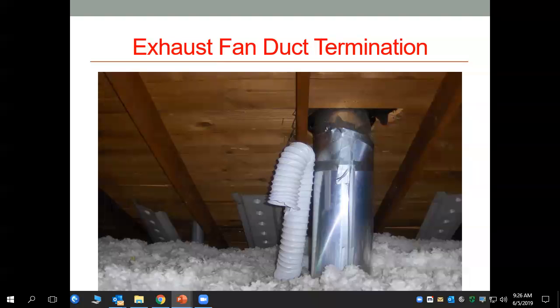And here's the way that we used to do exhaust fan duct terminations, which you could see, and still see in some municipalities. It's not a good way to do it. We always thought doing it that way was really more professional, but if you think about it now, where's that hot, humid air going? It's going right into the insulation. So turning it up is probably better. We just didn't want to fill it up with insulation.